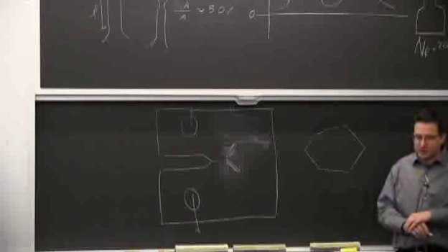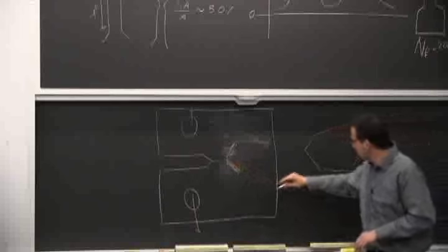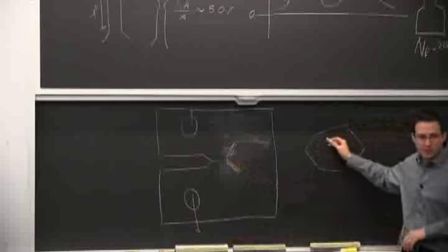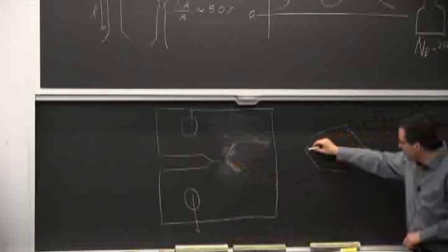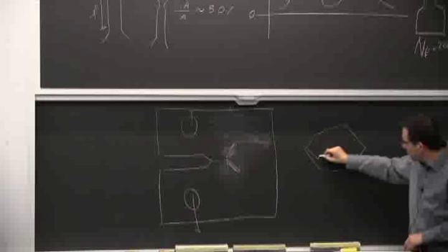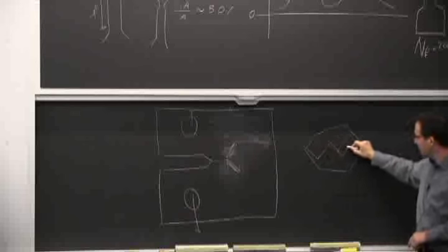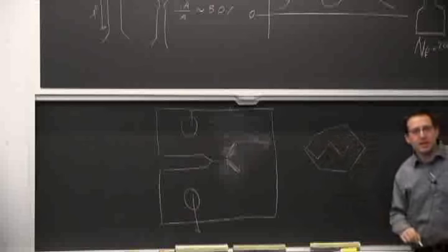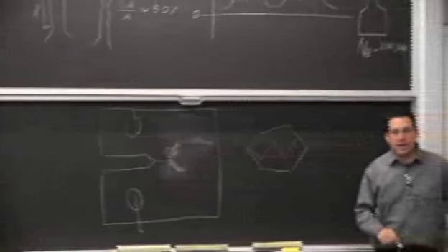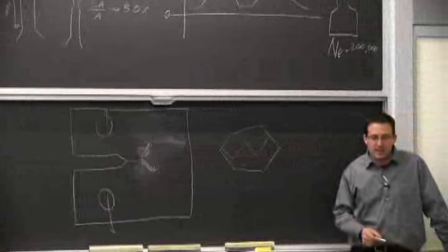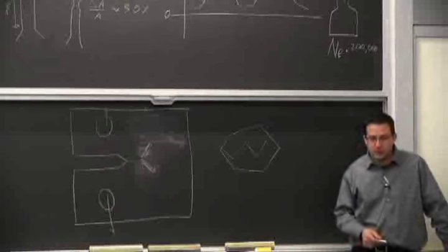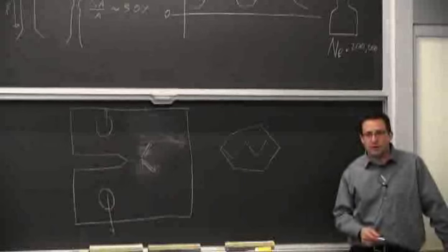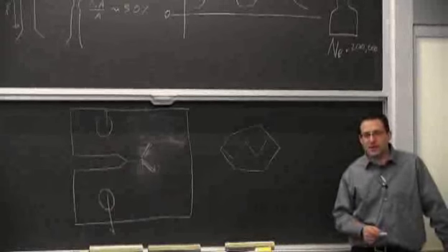And that's why, at small plastic zone, if the plastic zone is only within a grain, the crack will be forced to follow certain characteristics, certain planes in the crystal. And that makes this part of the fracture more difficult to predict precisely.